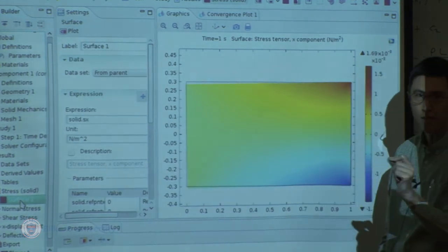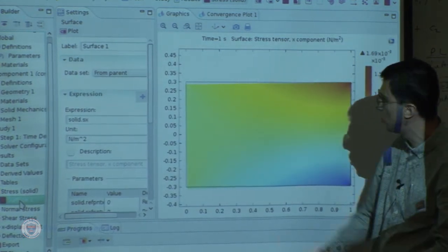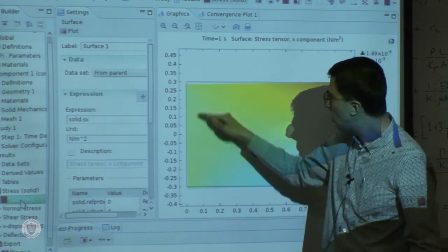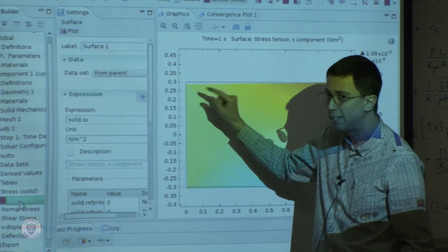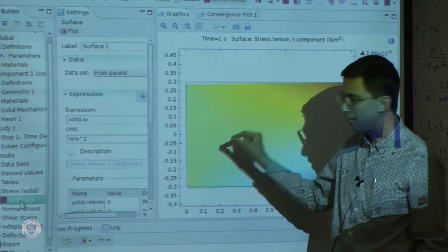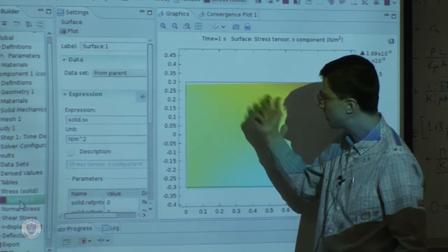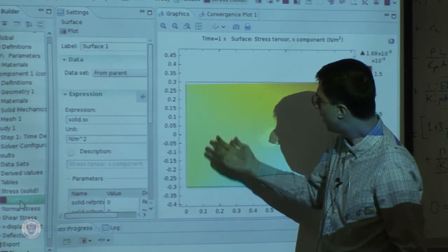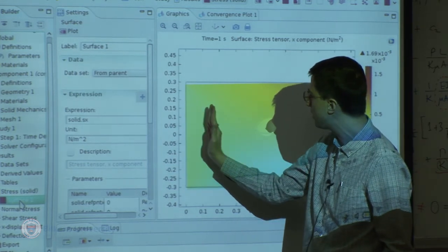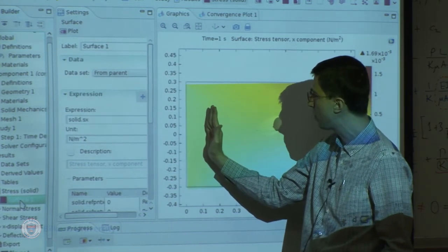I said that when I integrate the stresses, they should be equivalent to, statically, just a vertical force. Of course, locally, the stresses will depend on how I distribute that or represent that force. But statically, in a sort of Saint-Venant principle manner, whatever the particular distribution is will only be an end effect, and it will rapidly diminish as I move away from that end.